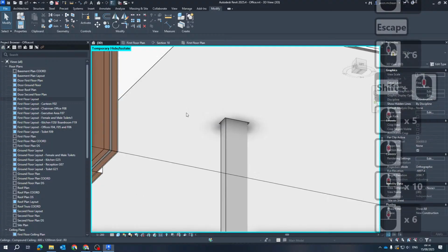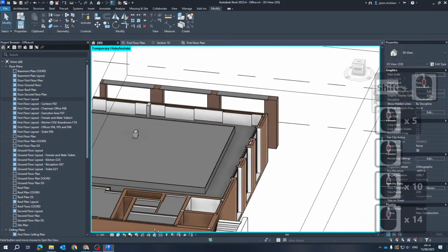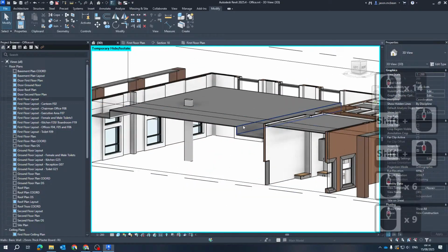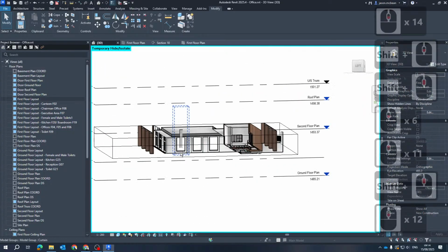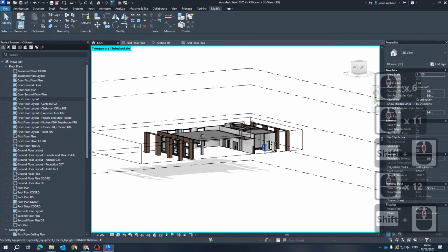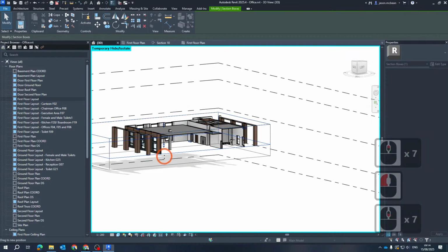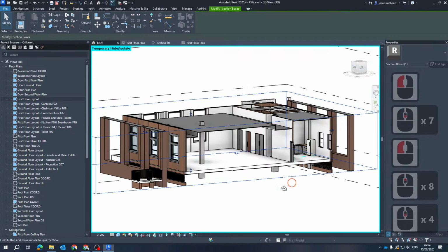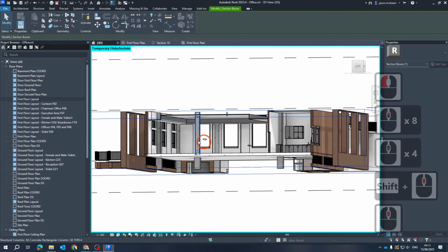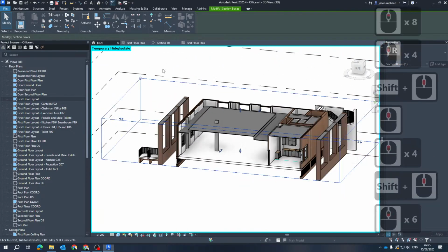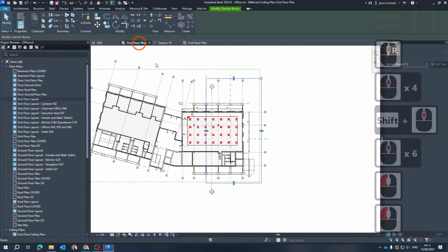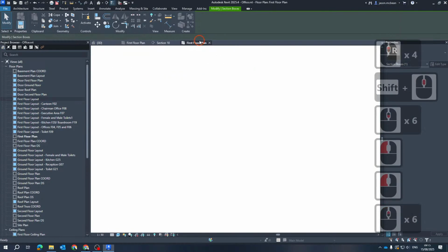Here I've provided my buffer around. Okay, so that's quite neat. Don't waste your time trying to use 3D light fittings for this exercise. That's something that if you're going to spend a lot more time detailing it 100%, you can go to town. Okay, so that's just a great little workflow on how to go and set up your ceilings and how your lighting will work with this and your floor finishes.